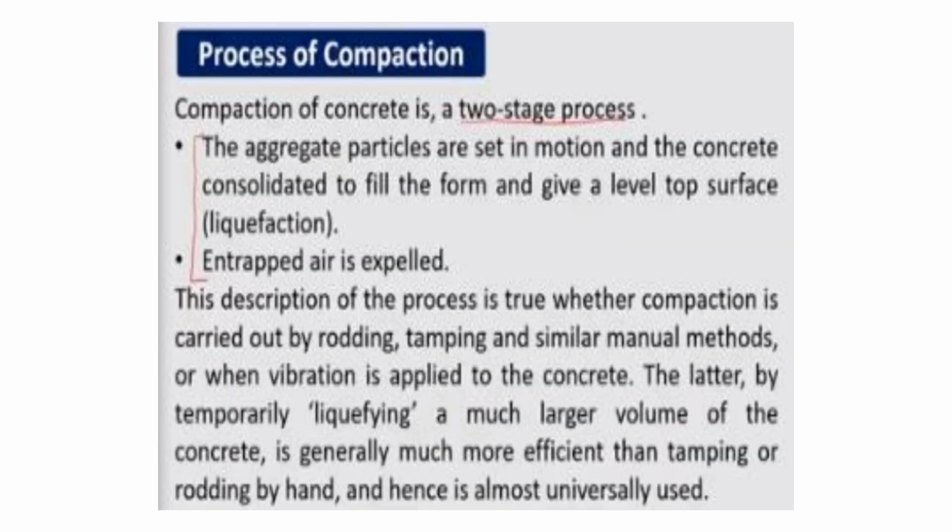So it is basically a two-stage process, okay. The compaction of concrete. Firstly, the aggregate particles are set in motion and the concrete consolidated, okay, to fill the form and give a level top surface, which is also called liquefaction, so that the water comes up, okay. And second stage is the entrapped air is expelled. So we will see more about this in the coming slides.